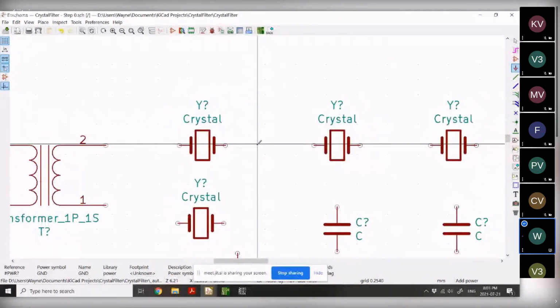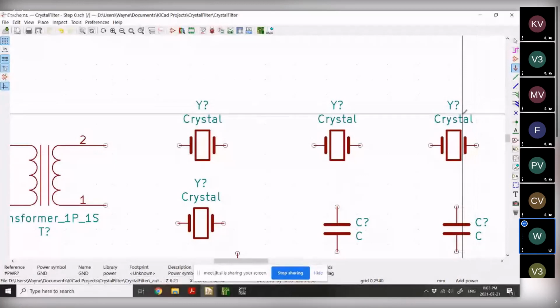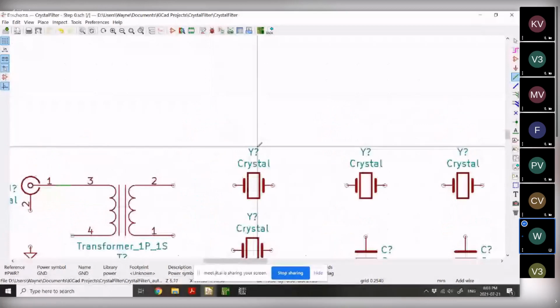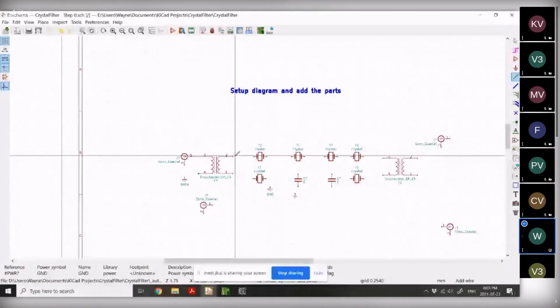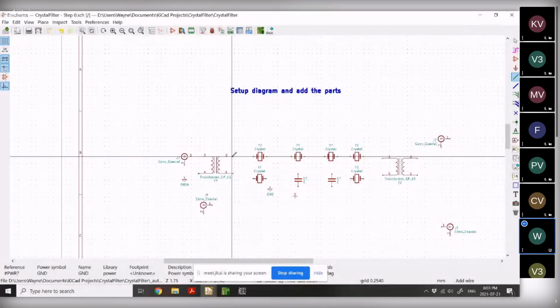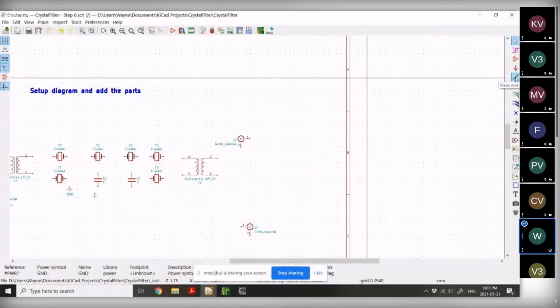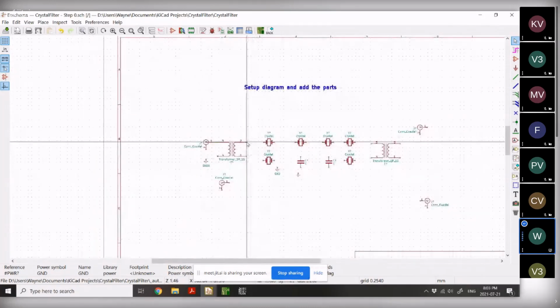Now, before I move on from the symbols, you can stop me now, and now's a good time because I'm going to start wiring stuff and show you the problems with it. Okay, so wiring sounds simple, but if you take the picture out to a decent distance for drawing, and then, oh, I'm sorry, I forgot to say, first thing you do is you click on the place wire symbol. It also says place wire under it, so it's easy enough to find. It's the green one. And you place a wire.